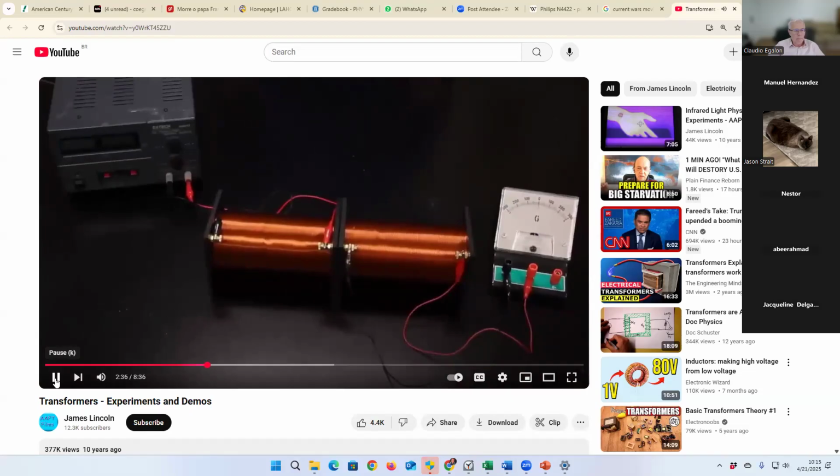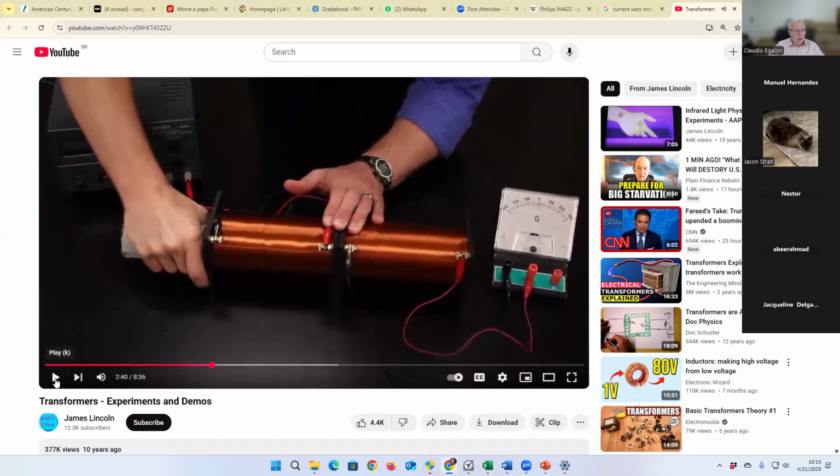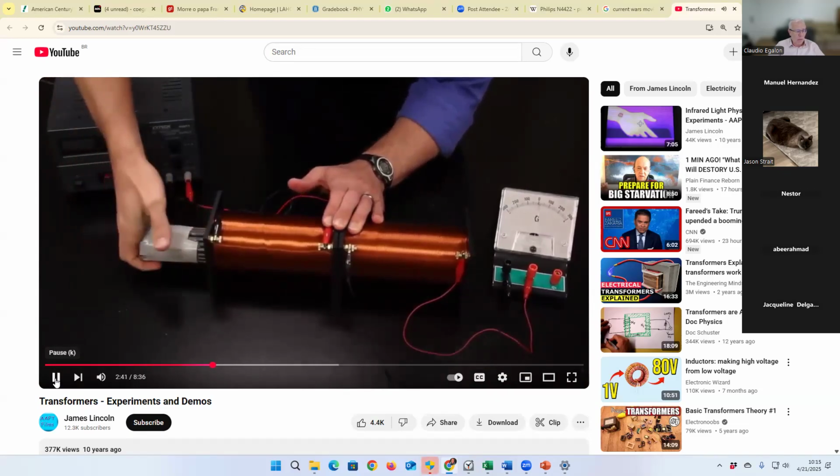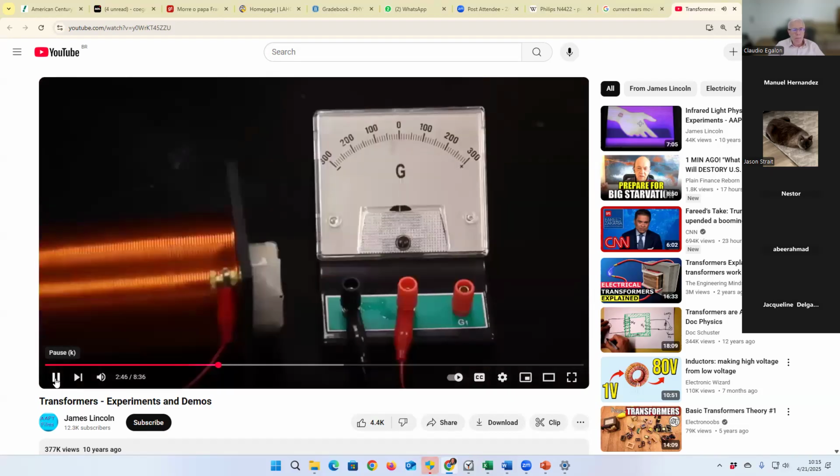The magnetic flux between the coils is greatly increased when a soft iron bar is added. Here you go. This improves the efficiency. Here's the iron bar. It's very important because this iron bar concentrates the magnetic field generated by one of the coils, improving the efficiency of the transformer by strengthening the field and preventing it from diverging out and being wasted. See that? Much better. The deflection is much more intense, right? He still didn't connect these coils to the generator. Right now, he's just connecting the coil to a power supply that provides a very quick current change, right?